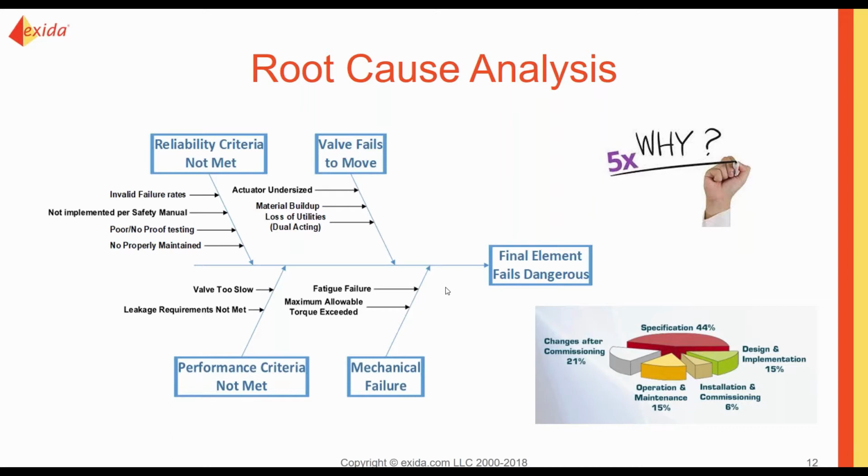So for things that go about reliability not being met, the final element assembly can appear to be working properly, but it's not really providing the performance. So if you have invalid failure rates, you didn't design it to the safety manual, you're doing poor or no proof testing, or you're not maintaining it, that will undermine the reliability. Valve not moving.